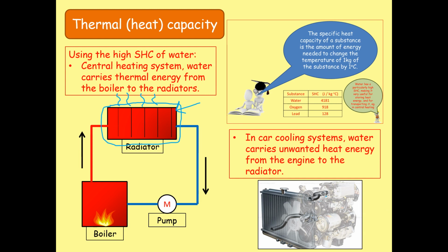As we do know, colder water would go down and hot water will move up. So we simply use this: we push in hot water from the top, we allow it to fall down through gravity, and as a result it is cooling down, and colder water will also move down, so it will go through the lower pipe, go through the engine, heat up, and get back into the cycle.